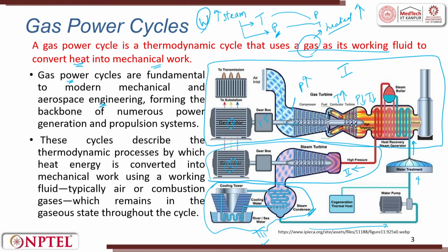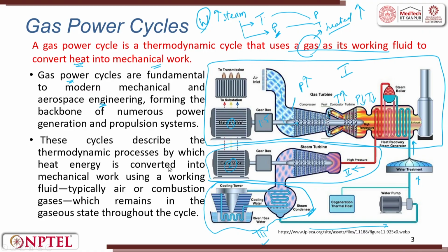The gas power cycles are fundamental to modern mechanical and aerospace engineering, forming the backbone of numerous power generation and propulsion systems. These cycles describe the thermodynamic process by which heat energy is converted into mechanical work using a working fluid. That is what I said. You have a working fluid, this working fluid you are trying to play with pressure and temperature, that is all. So, typically air and combustion gas which remains in the gaseous state throughout the cycle.